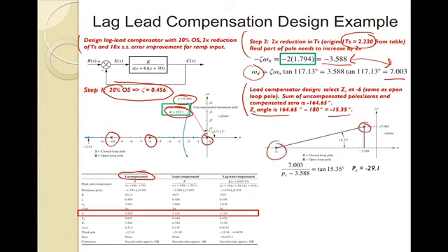We can essentially use that to find our compensator pole for our lead network, and then from this geometry we can find that the value of the pole is minus 29.1. Okay, so one comment, I think I just made a slight error here on the slide. So the sum of the uncompensated pole zeros and the compensated zeros is here, and so this ZC really, I believe that should be PC because that's our compensator pole.